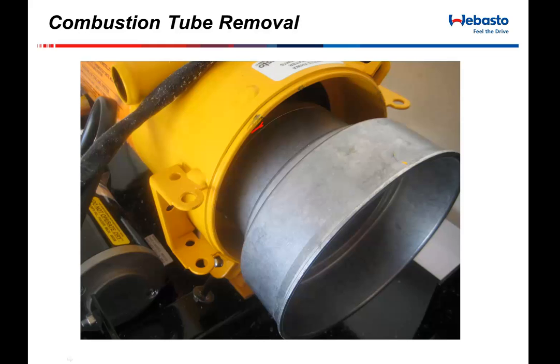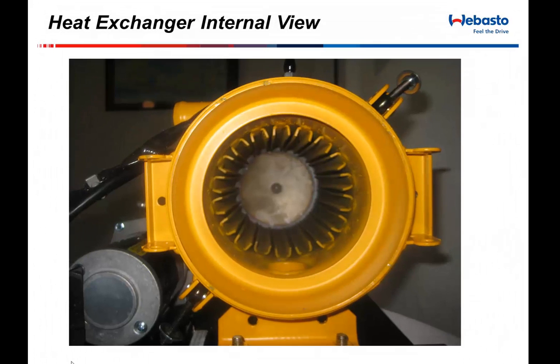But you can pull it out, slide the thing right out, and what you're left looking at is an empty heat exchanger. Take a wire brush to it. If you've got any kind of carbon buildup on the inside of it, go ahead and get that stuff out of it. Use a shop vac, whatever you have to do.